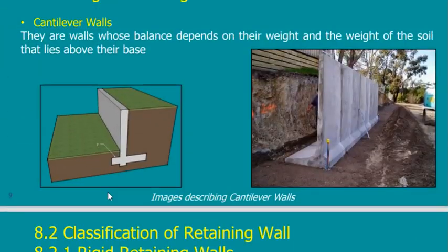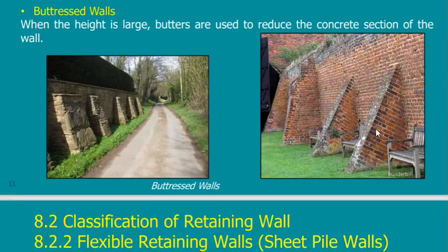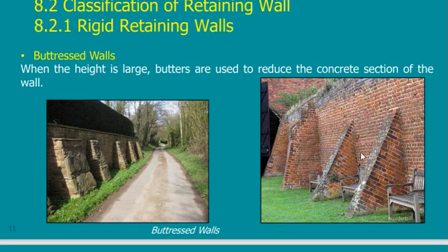So if we go to this drawing, instead of putting the counterfort on this side, I put something outside. In this case, it is also a counterfort, but on the opposite side, and it will be called a buttress. What is the role of it? It's a stiffener, placed every fixed distance, but in this case, it will be carrying compression, not tension. So in this case, these are the buttresses. But of course, these are not covered by the soil, so I will see them.